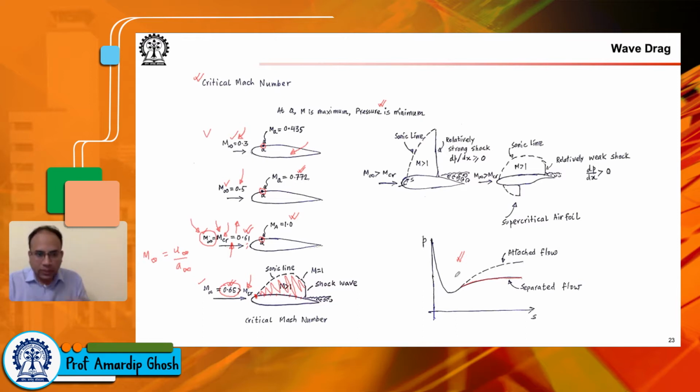Okay, so this whole thing that is happening, the supersonic state, the shock wave, the flow separation, all of these influence the distribution of pressure on the wing surface, and you will see that a large increase in drag occurs primarily due to the separation of the boundary layer, which follows the discussion of pressure drag due to flow separation, as we have seen before.